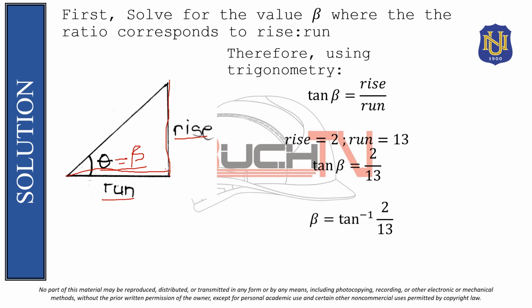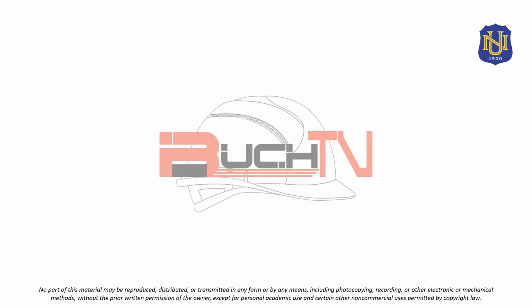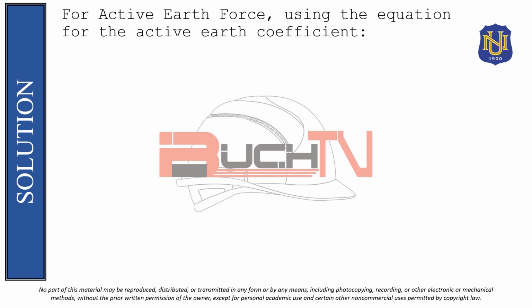Therefore, we have beta is now equal to tangent raised to negative 1 of 2 over 13. Solving this using our calculators, we will have a beta equivalent to 8.7462 degrees. So we will now have our beta, which is 8.7462 degrees upward from the horizontal. We can now solve for the active earth coefficient using the equation for sloping backfill.